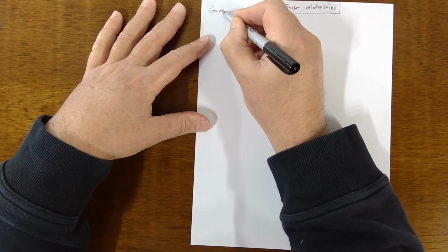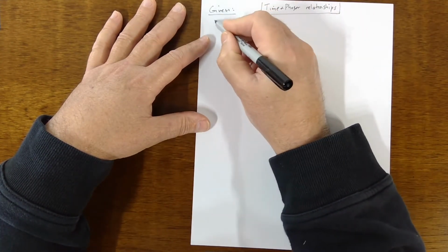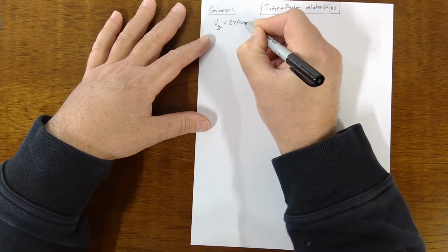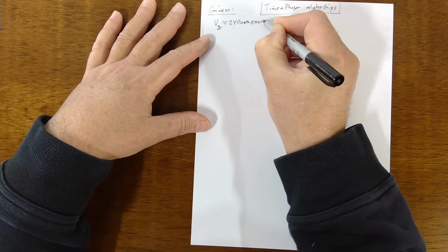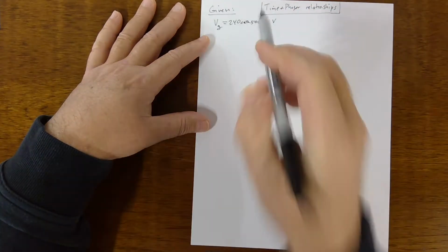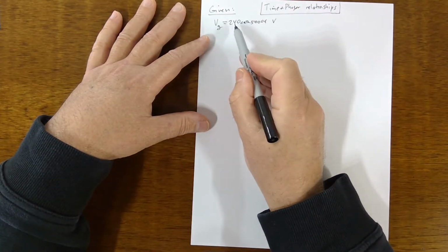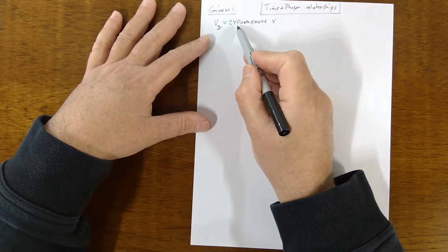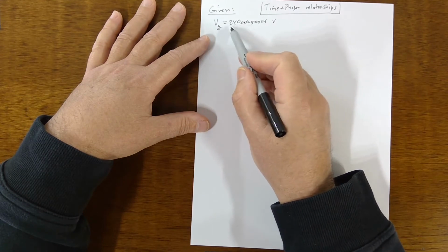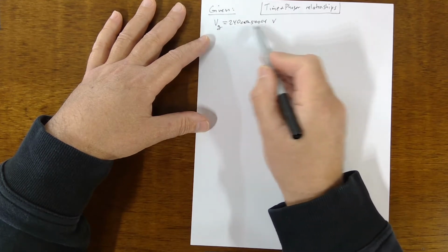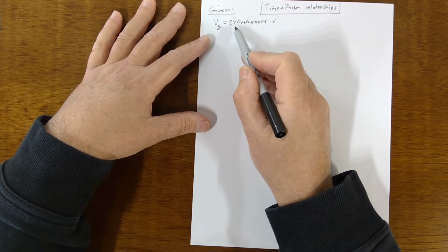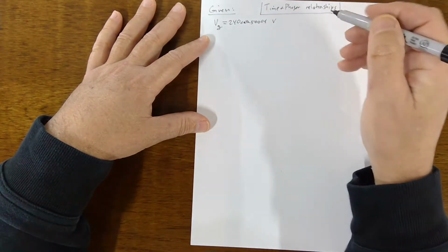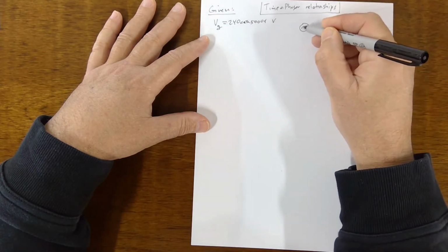So here we're given a time domain signal. V of this generator is 240 cosine 5,000 t in volts. So this is a trig function, so 240 is the peak, right? Well, if they haven't told you otherwise, although they could, in theory, write this trig time domain thing and use an RMS value in here, but here it's peak. So this is a generator V sub G.